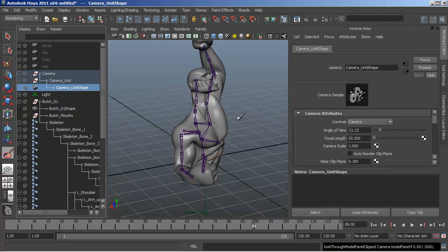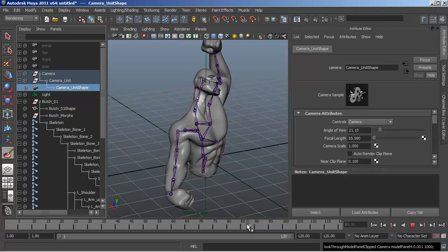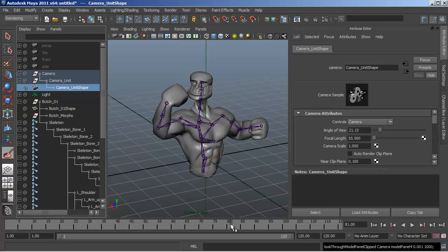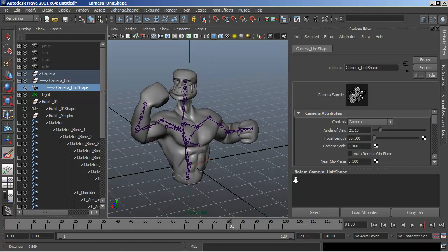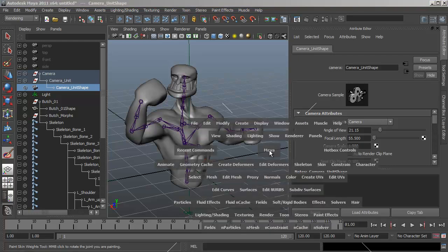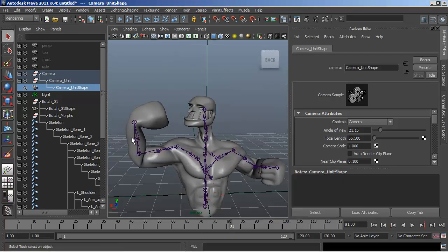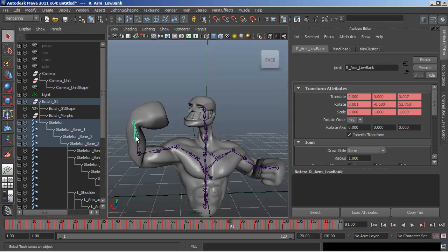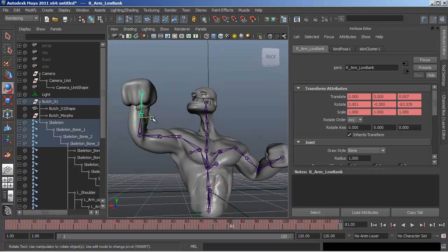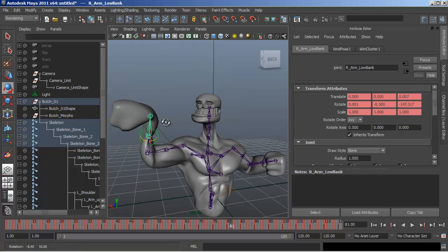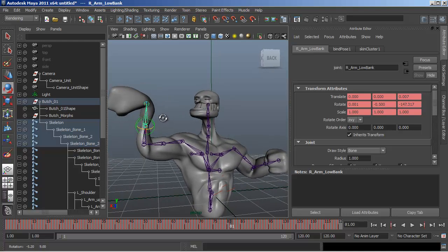One of the advantages of Maya is the dual quaternion skinning method. So to showcase that, let's go to some frame where we can force a pinching to occur. Let's get back to Perspective View and select, for instance, this joint, and let's quickly disable the Alt key so we don't change anything by mistake, and just rotate it to force a pinch. Let's twist the view a little bit. Okay, here you can see clearly the pinching, which is a result of the linear skinning method.